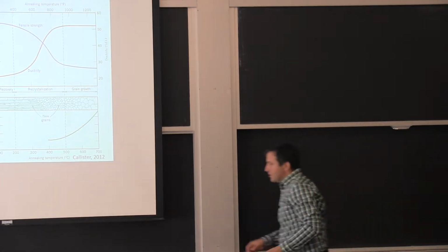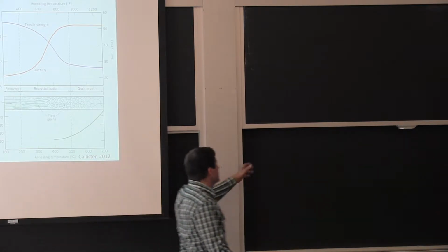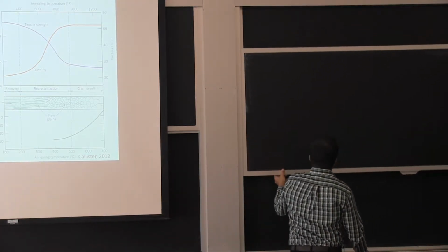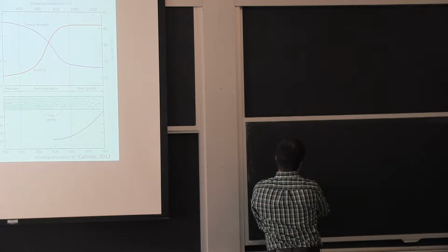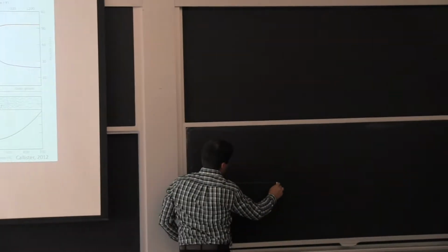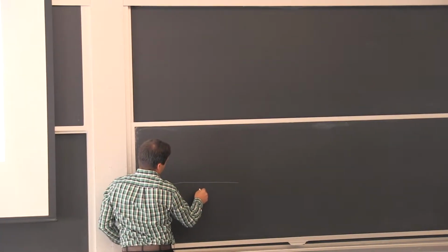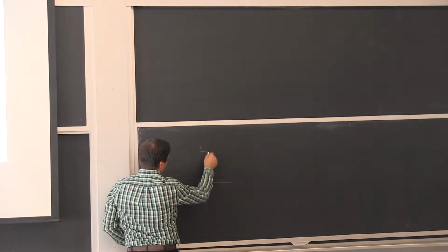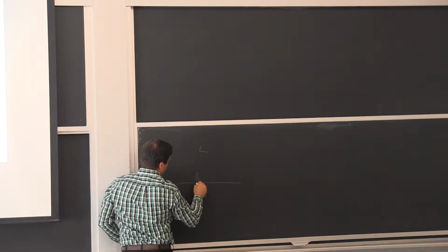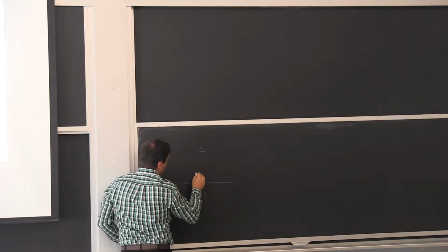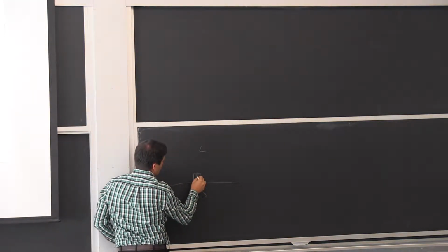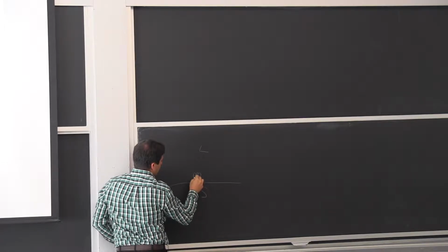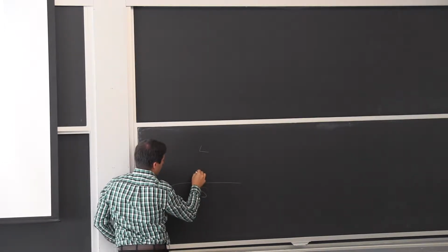So let's go through this, because that's why we use aluminum silicon. We can get relatively fine grains, and the reason is we solidify two phases. So say I have the aluminum and silicon, instead of just growing, I have the solid here, and I have the liquid, and what I'm doing locally is growing the alpha phase and the beta phase by just moving ahead of the solidification.